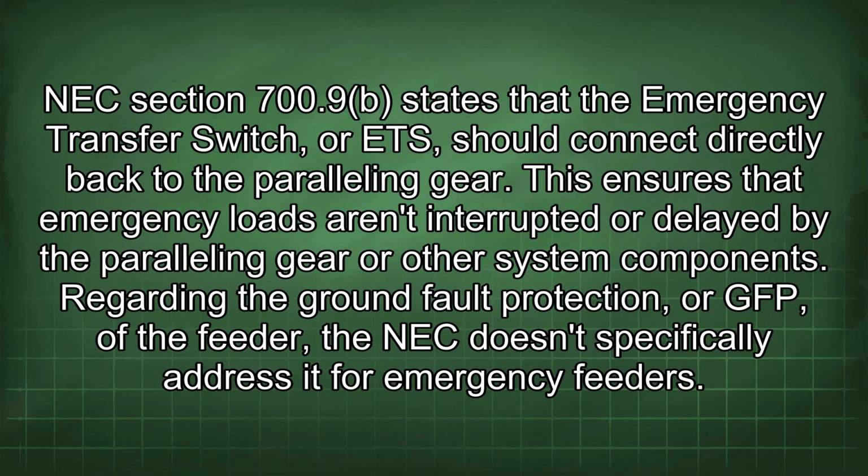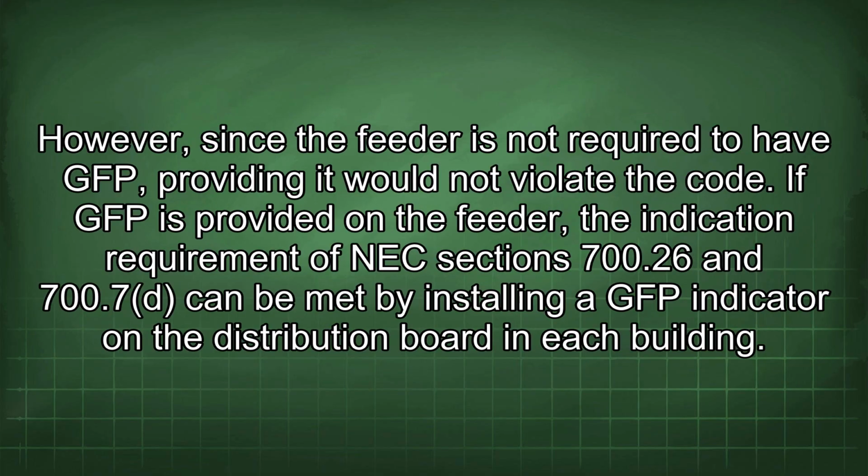Regarding the ground fault protection, or GFP, of the feeder, the NEC doesn't specifically address it for emergency feeders. However, since the feeder is not required to have GFP, providing it would not violate the code.